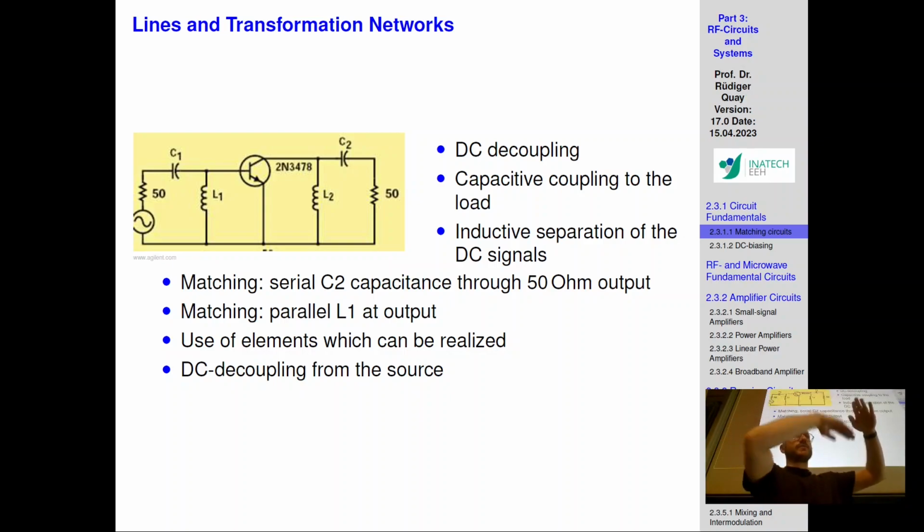MIM-caps. Basically, they have a certain microstrip line, underneath you have a certain isolator and another microstrip line, until you reach the end point of your device, so that your EM wave spreads around and is transferred to the lower capacitor, and the coupling occurs. We'll know what coupling is. The coupling is, if your devices are in the near field, the EM waves will couple, will go from one connector to the other, and in between this isolator you will generate a MIM-cap, a metal insulator metal capacitor, and that's why they have a certain loss.